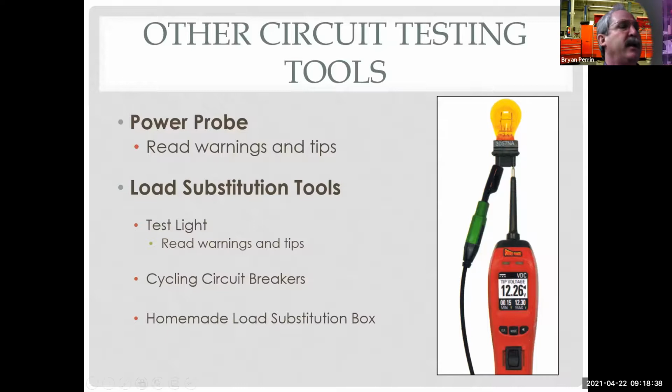The other thing it has is a rocker switch on it. And this rocker switch can be used to apply power or ground at its tip. It also has a separate lead hanging on the side of it that is a ground lead. So this allows me to connect it to here, connect the Power Probe to here, push the rocker switch to power, and watch the light bulb come up, or watch the window go up, or watch fill in the blank.